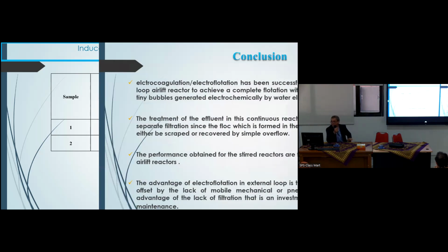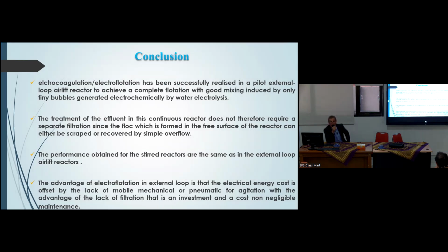So the final conclusion: electrocoagulation, electroflotation has been successfully realized at pilot scale in an external loop airlift reactor to achieve a complete flotation. We have achieved a complete flotation with good mixing, using only tiny bubbles generated electrochemically by water electrolysis.